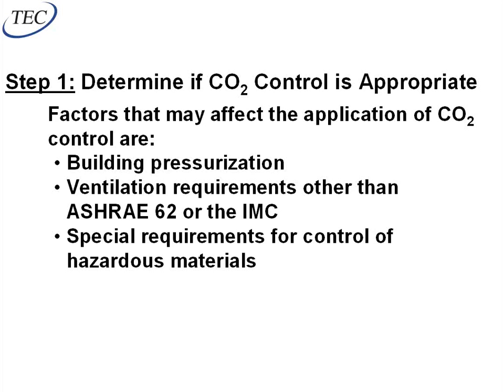So when I set up the minimums on my damper, it's going to be the minimum of what I need for my CO2 system or what I need to pressurize the building, whichever is greater. And then the other thing to think about is if you have areas of the building that have hazardous materials, those are areas you're not going to mess with. You're not going to start messing with the ventilation in a laboratory or something like that, or a dry cleaner. Leave those buildings alone. Don't touch those buildings.